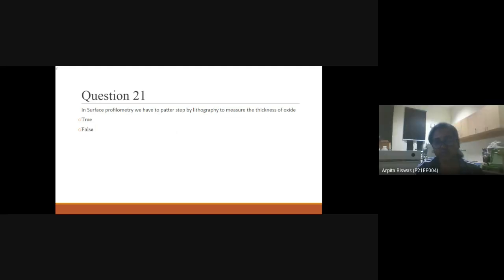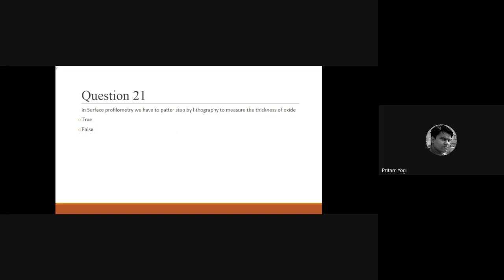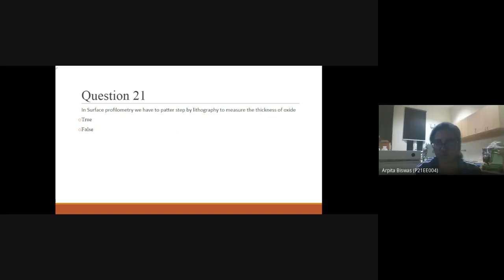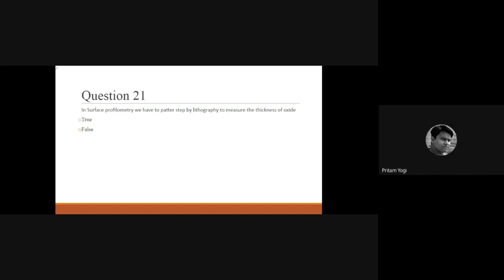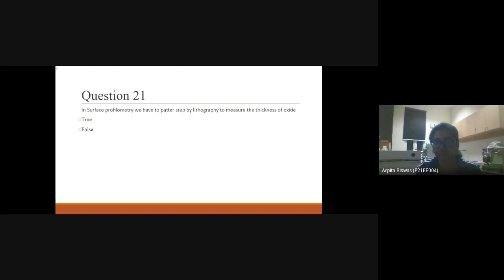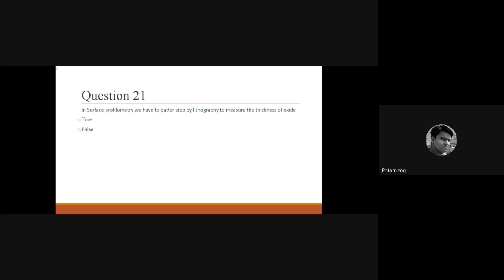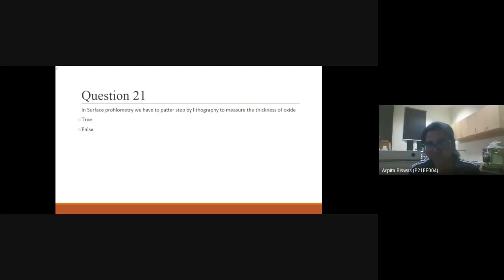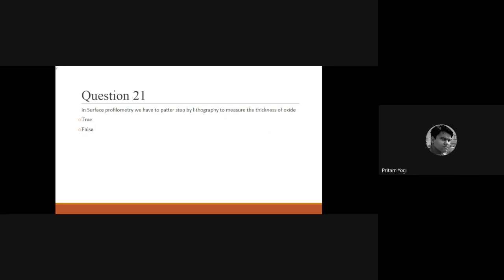Okay, and what about the temperature and time? It is called 100 degree soft bake process, right? Soft bake is after the spin coat. Yes, but I am talking about just before the spin coat. We can put the wafer for 1 minute to just remove the moisture from the wafer. Then spin coat, then soft bake. And what about the time and temperature? I think 110 degree for 1 minute soft bake.